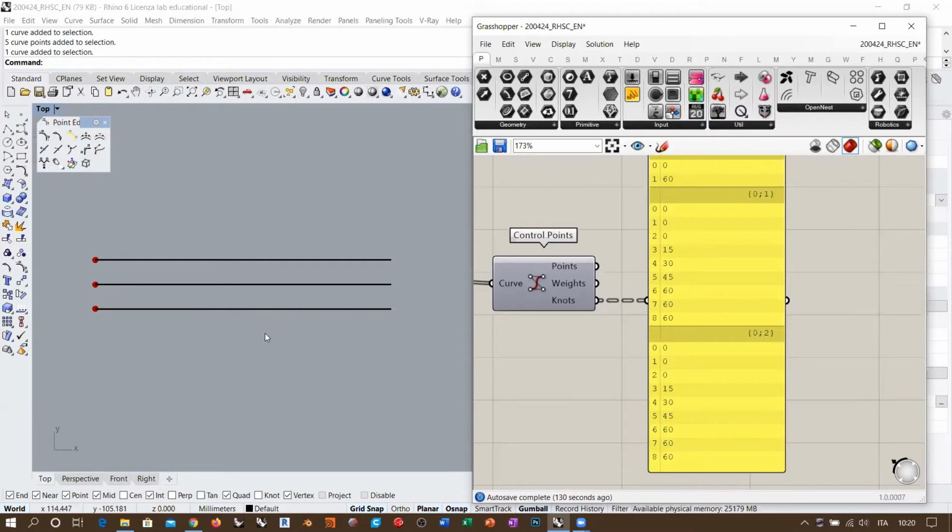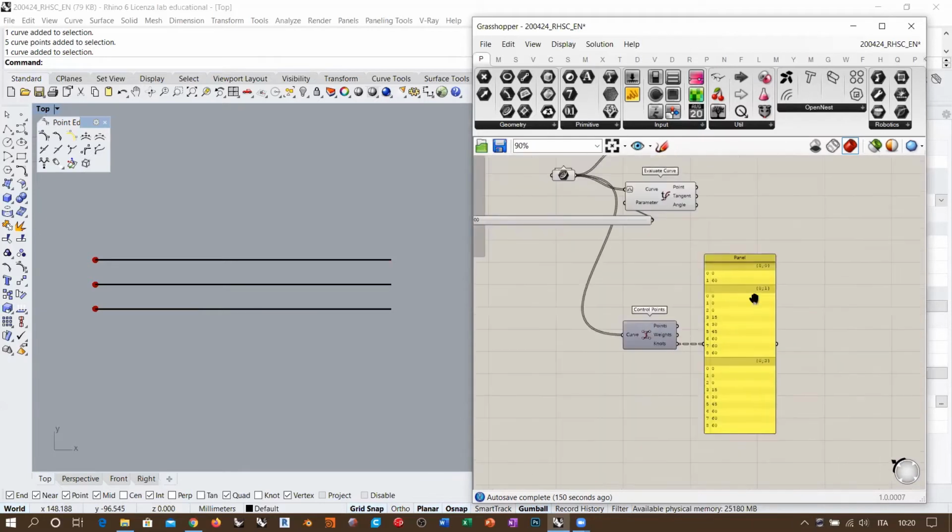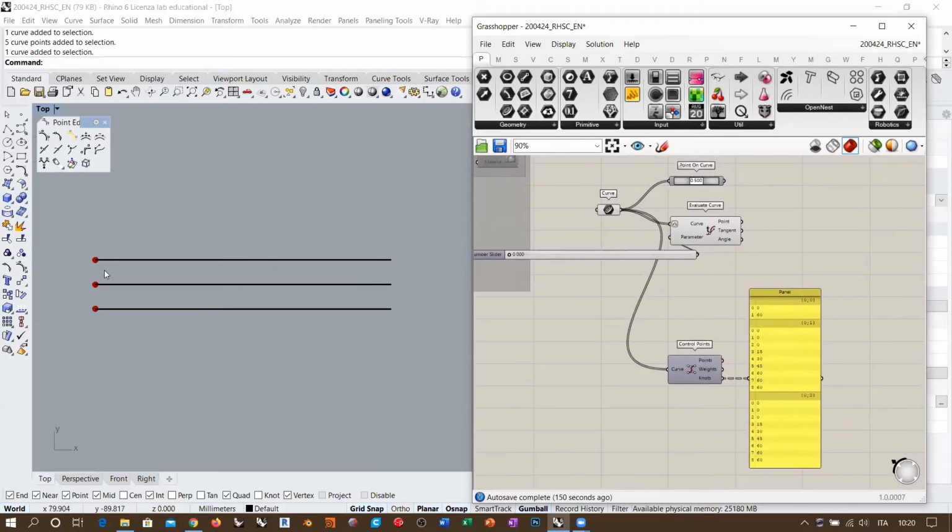So it is not that the uniform knot vector means physically equal length spans along the curve, because we are not talking geometrically, we are talking topologically. And topologically everything depends on the distribution of control points. So these points here.